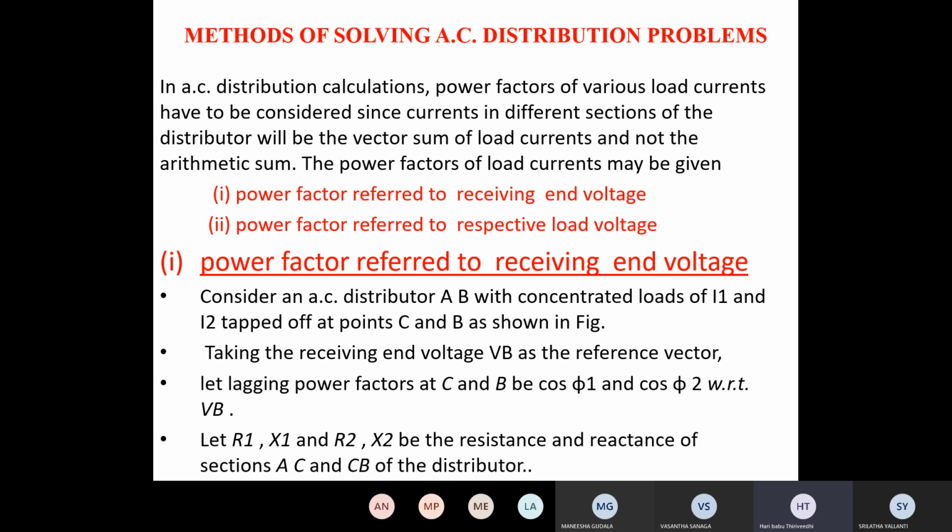Switching equipment requirement is less for radial type, because not many equipments are used, but it is very high in loop type. Why? Because every loop section has its own sub feeders, so we have to provide switching equipment, I mean protection devices.